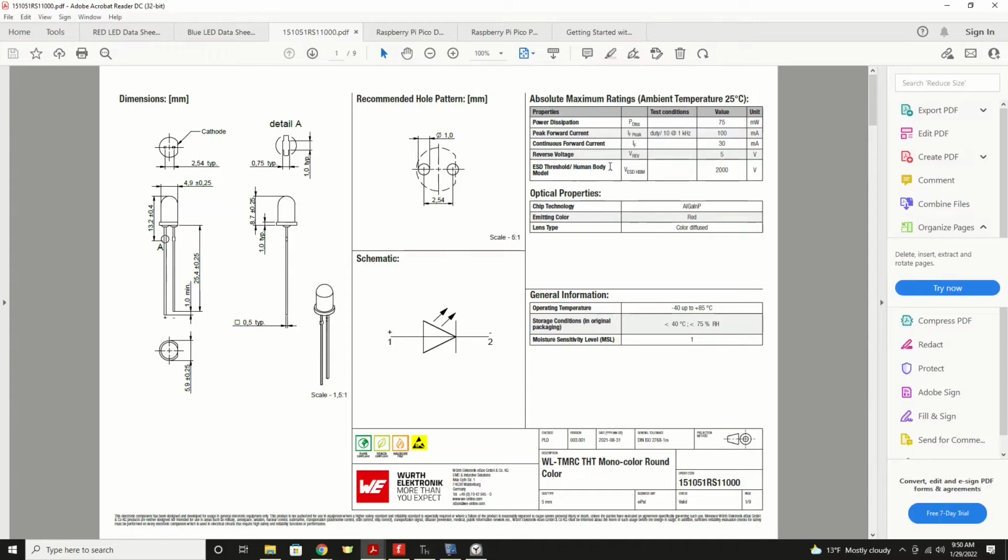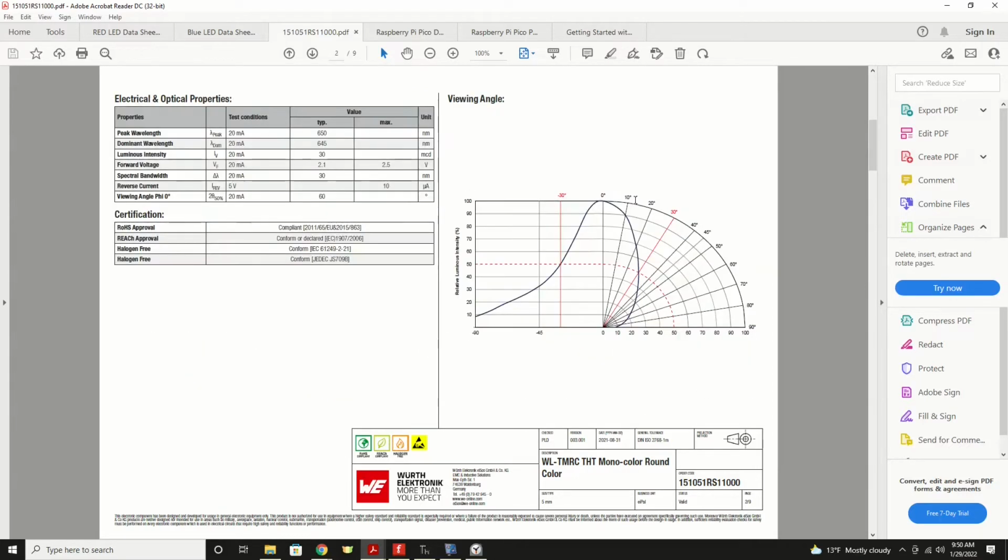But again, that's not telling us enough information from which to make our calculations. Here we're going to look at our forward voltage to get what they considered their test conditions of 20 milliamps. Their forward voltage was 2.1 volts. Here's your indicator of what this value means, V. So at 2.1 volts, we can achieve 20 milliamps of current, and that ran on their test data.